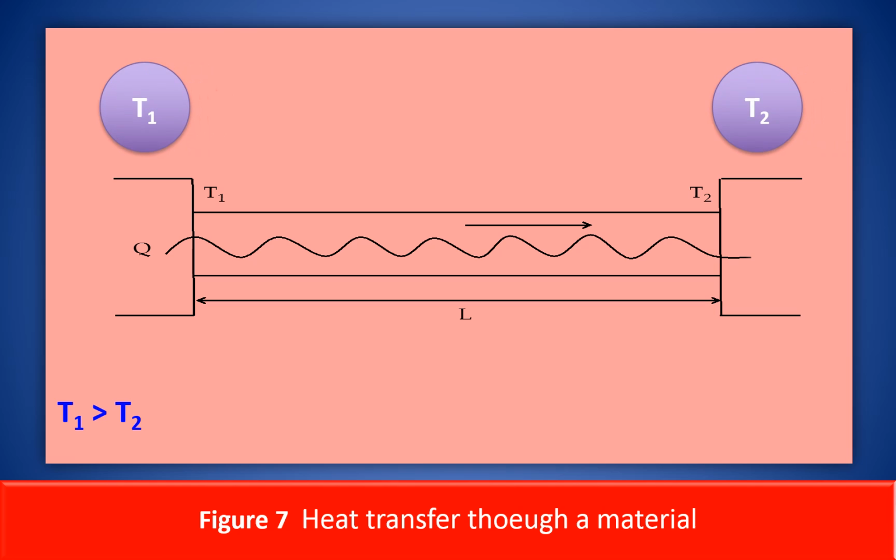This figure illustrates pictorially the placement of the two rods at the same higher temperature T1 and the heat conduction process. The rate of conductive heat transfer is faster in copper due to its higher thermal conductivity as expressed by the equation Q is equal to minus kA (T1 minus T2) divided by L.